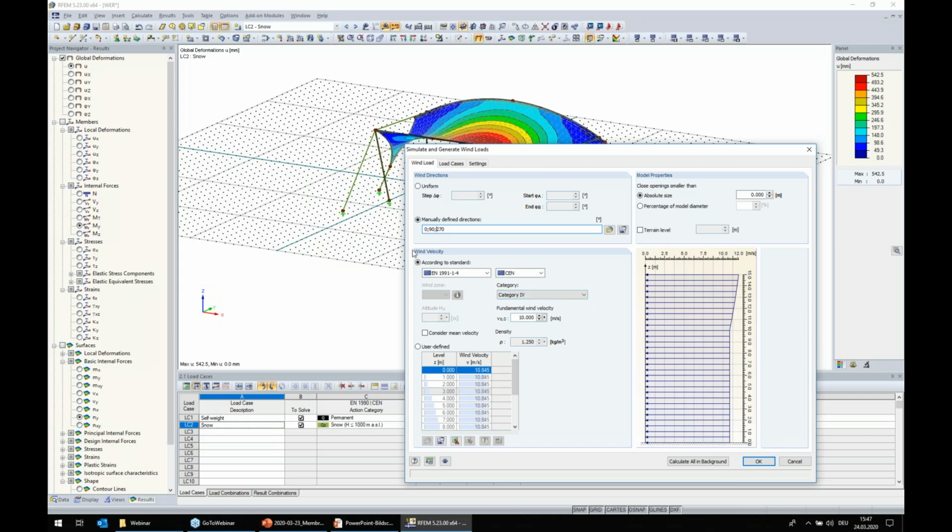And here in the second part we have to define the magnitude of the wind. We have to say strong wind, not so strong wind. For this, we offer here, let's say, a code box. You can select between Euronorm, American standard, and Canadian standard.